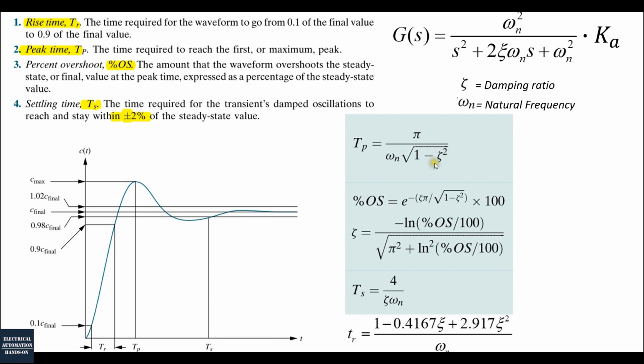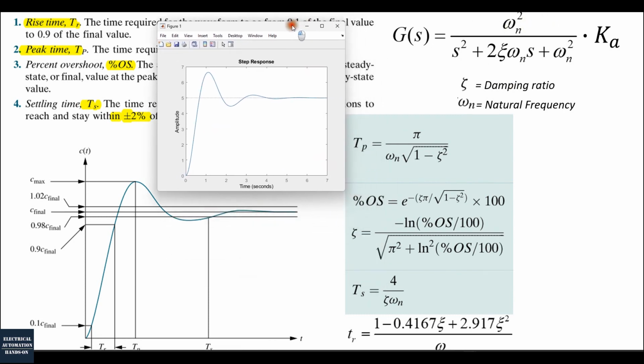And once we have the damping ratio and we have the TP, then we can get this natural frequency value, right? So basically, we can use the overshoot and the TP. We can have this second order transfer function. Okay, let me use the bump test from this Matlab time response, and let me demonstrate how we can get this TP and overshoot.